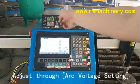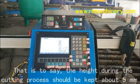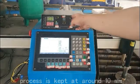Adjust through the arc voltage setting. That is to say, the height during the cutting process should be kept at about 5 mm. The positioning height during the arcing process is kept at around 10 mm.